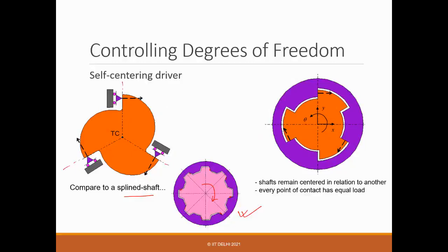You realize that given the nature of the force, one nesting force is actually good enough, because all the directions are in the clockwise direction. So an anti-clockwise moment will be good enough. It will make sure that there is contact all the time at these points.